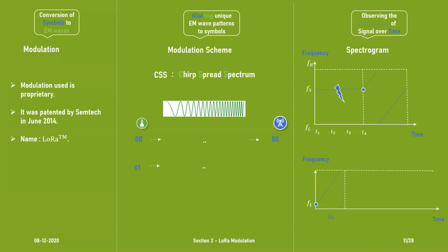However, if I want to transmit 0, 1 from the transmitter, after chopping my chirp into two parts, the start frequency of the first chop chirp is this time not F1, rather F2. That's the subtle difference that you see in all the different chirp combinations. When you are using 1, 0, just notice the start frequency. This time it does not start with F1 or F2. It starts uniquely from F3. So that's how modulation in LoRa works. You just chop the chirp into two parts. The starting frequency of the first chop chirp uniquely defines which symbol you want to transmit. So the receiver, whenever it sees the starting frequency of the first chop chirp, will understand which symbol out of the four we want to transmit. So that's it. That's LoRa.